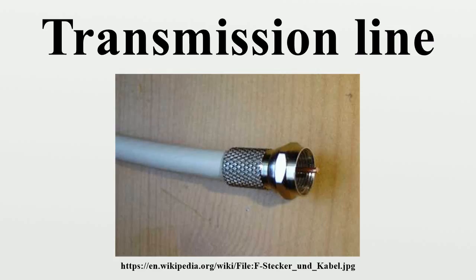In this configuration each pair uses two non-adjacent conductors. Other times it is used for a single, balanced circuit, such as audio applications and two-wire telephony. In this configuration two non-adjacent conductors are terminated together at both ends of the cable, and the other two conductors are also terminated together. Interference picked up by the cable arrives as a virtually perfect common mode signal, which is easily removed by coupling transformers.